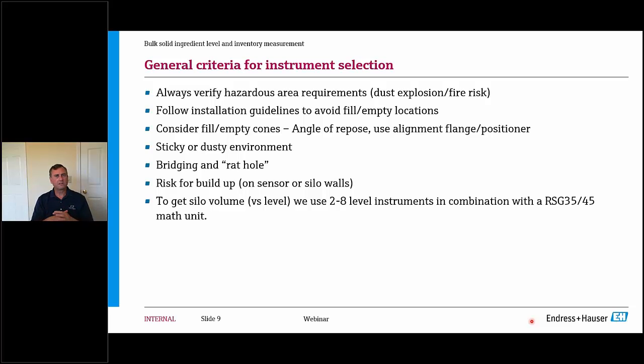A couple of the basic criteria that you need to look at as you start your journey, looking at what the opportunities are or what the options are that you have. An area that maybe is not always considered for solids is the risk of dust explosion or a fire risk. So when you're selecting equipment to go in there, you need to consider that. What is the risk level of a dust explosion or fire here? And then select the instruments that are rated for or have a certification to be allowed to use in that type of environment, which would then involve potentially also the wiring and conduits and other things that you need to consider.